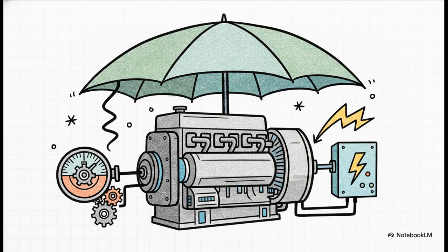So let's synthesize all of this into one single, unified view of a stable power plant. You now know exactly how this dynamic works for a single generator. The PID governor is out there driving the physical fuel rack to maintain your frequency and your active power. The AVR is simultaneously driving the excitation current to maintain your voltage and reactive power. And standing guard over both of them is that 95% knee point rule, fully ready to step in and sacrifice voltage to protect your incredibly expensive generator hardware from thermal destruction if the whole system gets dragged down.